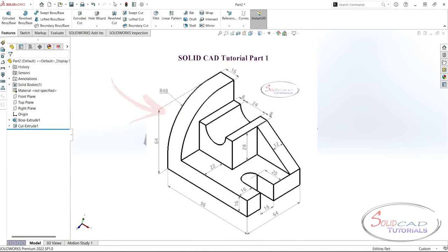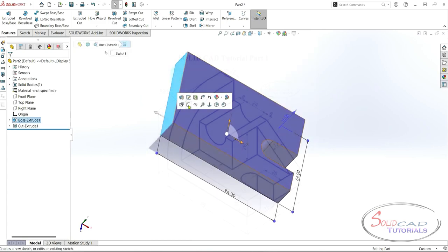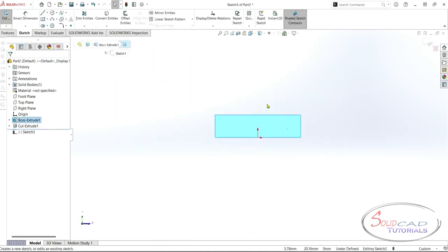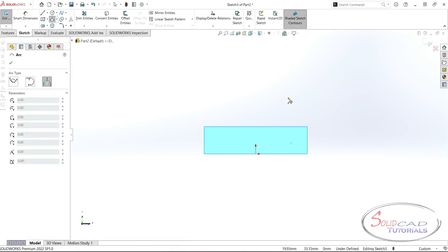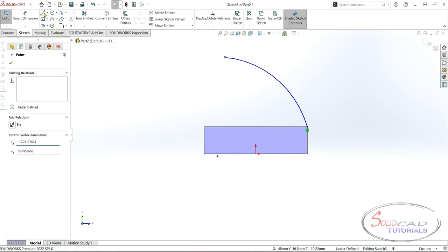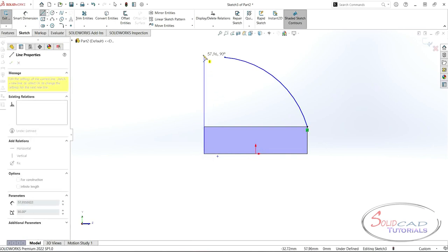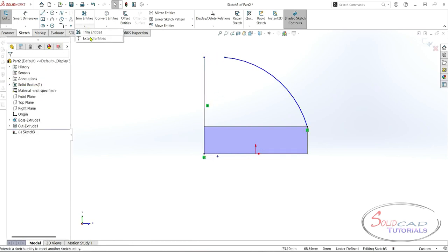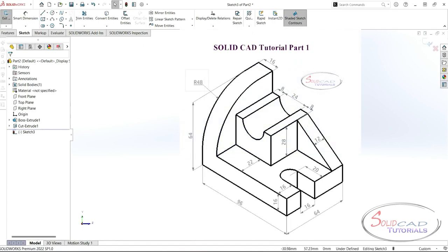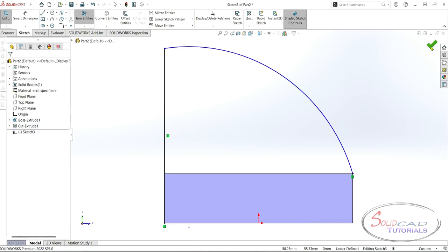Now, as shown in the drawing, we need to create a rib, selecting a face for the sketch to perform the rib by using the 3-point arc. For using the 3-point arc, select point 1 from the right upper edge of the base, and plot the second point on the left upper side. Draw a perpendicular line from the start of the base part which will connect us to the curve. Next, referring to the drawing, we need to enter the vertical length as 64 mm, and give a radius of 48 mm.